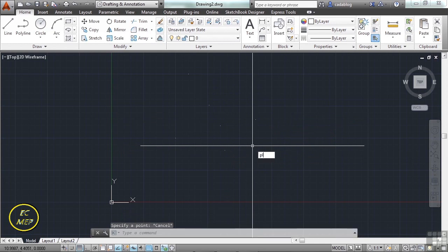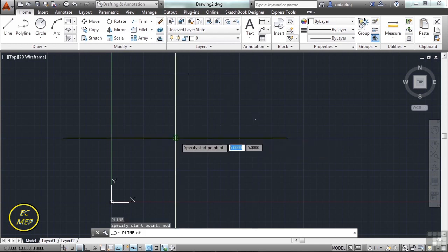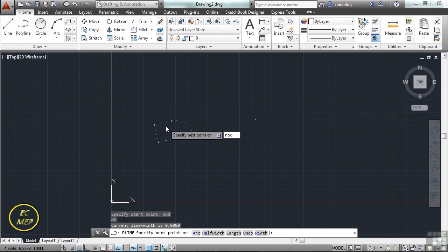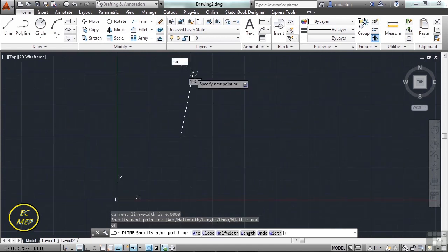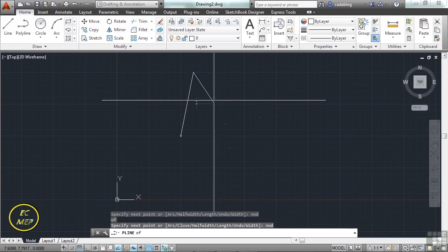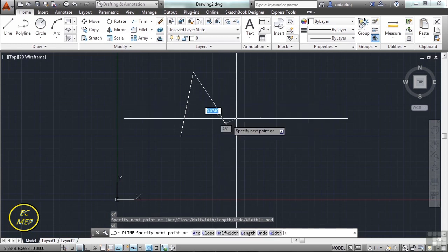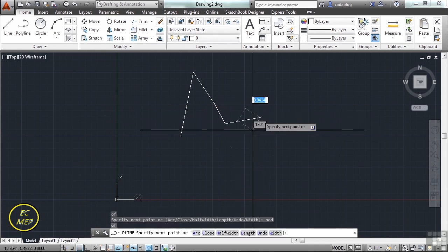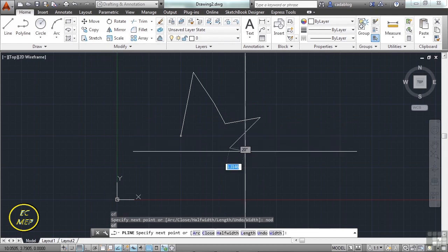Now start the polyline command and type in NOD for your O-snap, which will be a node point, and click on one of the dots. And keep doing that and just connect your dots together. What you're doing now is just plotting out these points and then connecting them by drawing them together with a polyline. And you can make various shapes, etc.